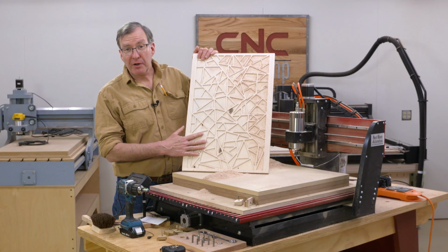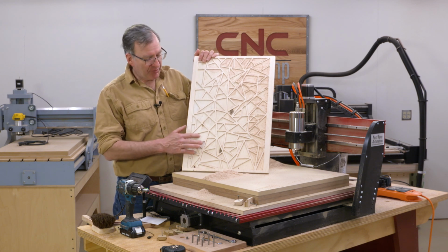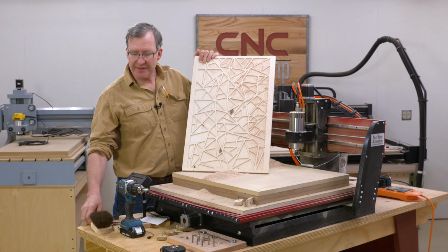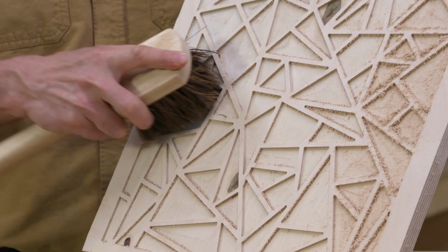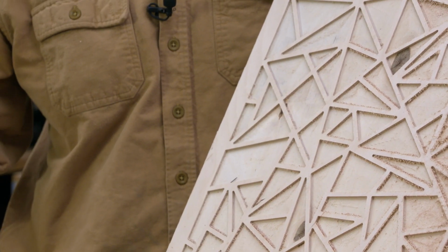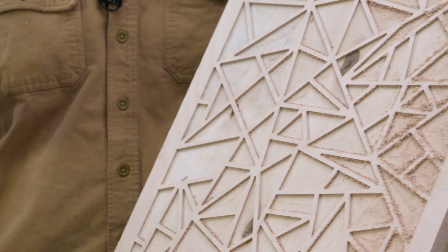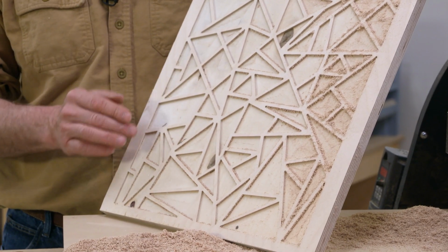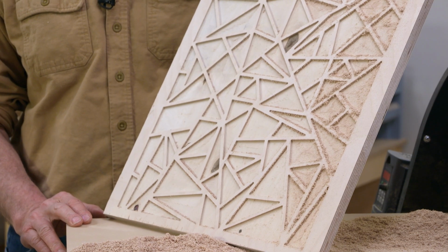Well, there's the panel for our future door. You can see lots of places for putting nice exotic woods. So what's next? Well, I'm going to take this Palmera brush and I'm going to really scrub it down to get rid of some of the little fuzzies within these openings, make sure they're nice and clean. Then it's going to be time for us to set up and start cutting the 1/8 inch thick pieces that are going to fill these openings.